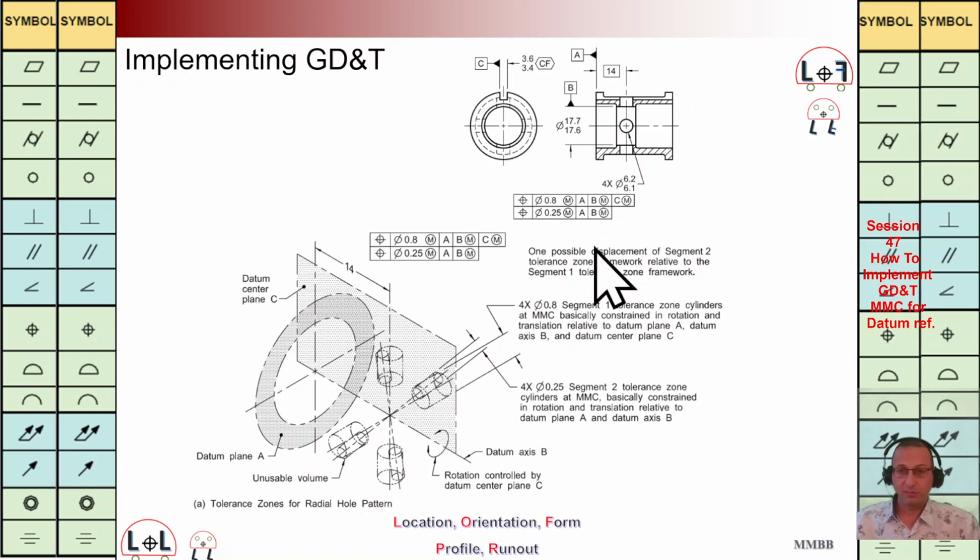And at bottom, yeah, we are going to have these two independent FCF. I should take care about B as well, not just orientation. Also, location with respect to B is important here because these two FCF are independent. It is not composite positioning control. It is two independent FCF.